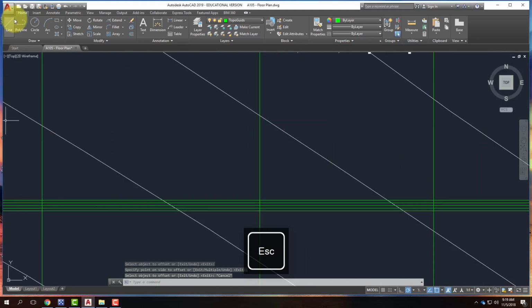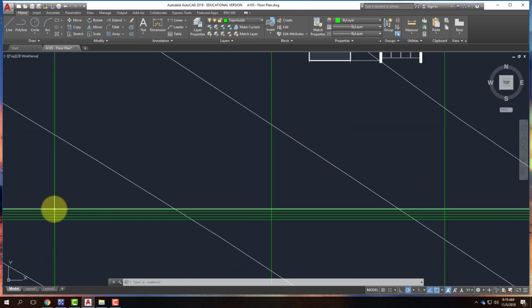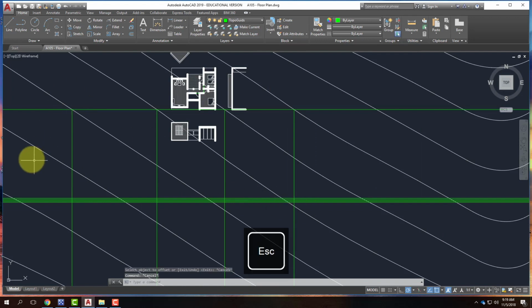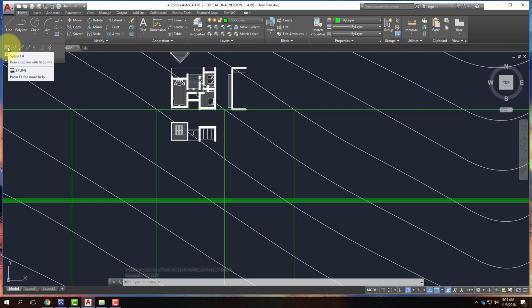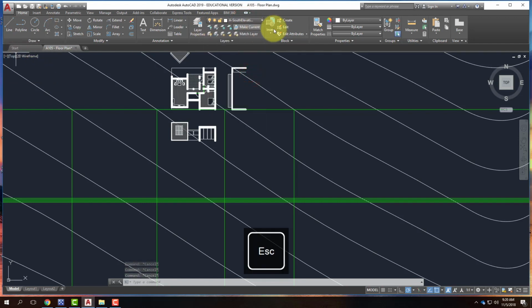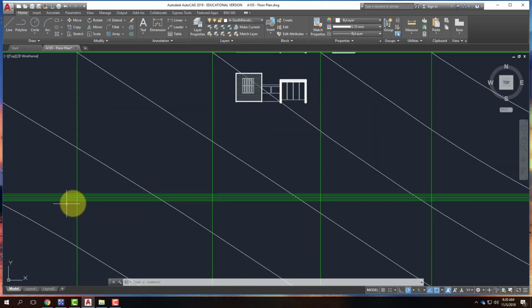So then I can create a curving line that starts at its highest point here and goes down at each one of these points. To do that in a smooth line, I'm going to use something called a spline. It's this one right here. It's called a spline fit, or if you just type spline, it will get you there. But before I do that, I want to switch over to the south elevation layer. And so that this becomes really obvious, I'm going to go ahead and change my thickness ahead of time, so you can see it as I create it.